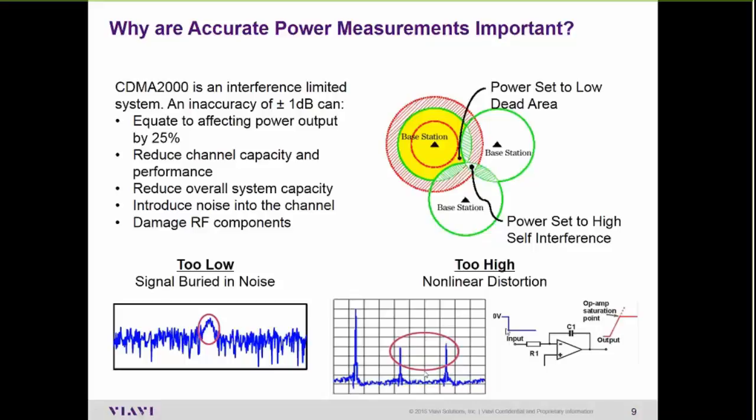And what you can get there is a lot of distortion that pops up. You'll see these spurs that'll pop up in the network causing interference issues. You can also damage your amplifiers by having too much input power into them. You get things such as clipping. It drives it past the saturation point. You get distortion in the digital signal. Your frame error rate rises. All those types of issues from that.